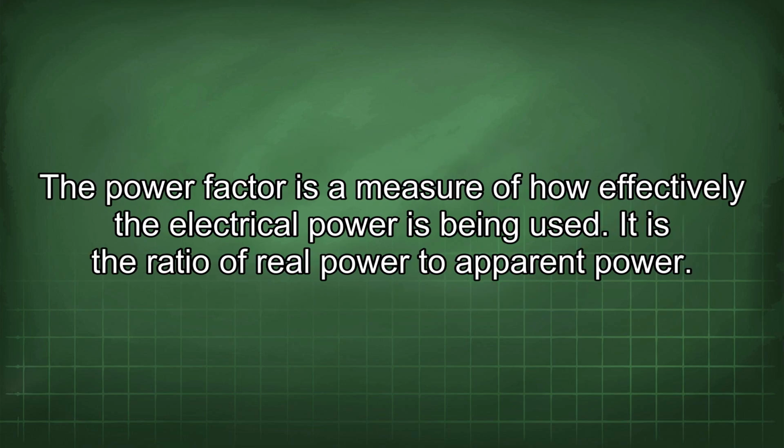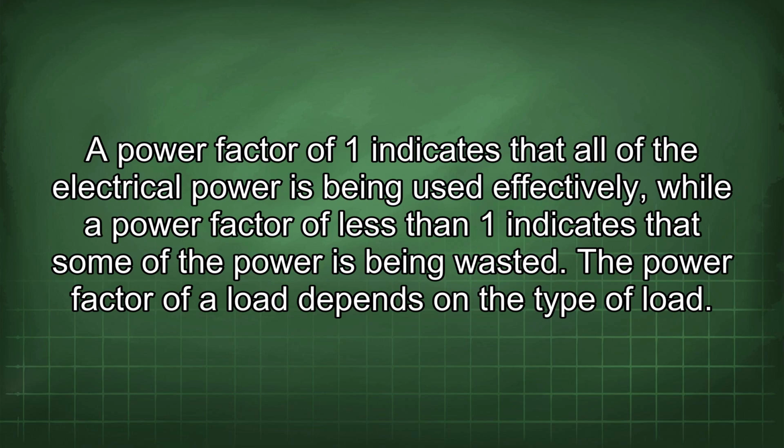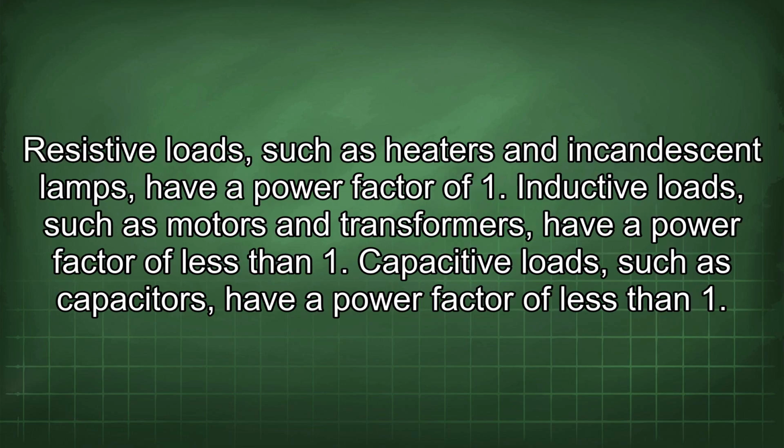PF represents the power factor of the load. The power factor is a measure of how effectively the electrical power is being used. It is the ratio of real power to apparent power. A power factor of 1 indicates that all of the electrical power is being used effectively, while a power factor of less than 1 indicates that some of the power is being wasted. The power factor of a load depends on the type of load. Resistive loads, such as heaters and incandescent lamps, have a power factor of 1. Inductive loads, such as motors and transformers, have a power factor of less than 1. Capacitive loads, such as capacitors, have a power factor of less than 1.